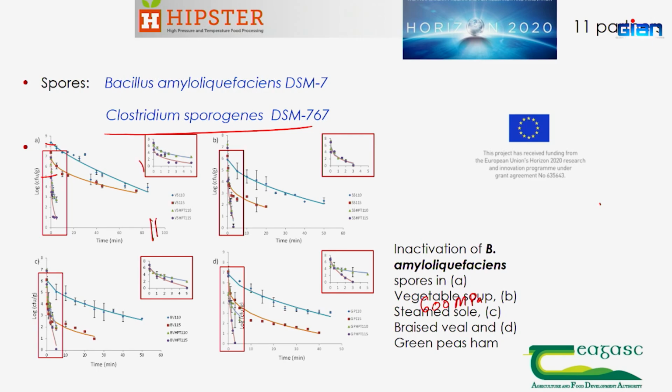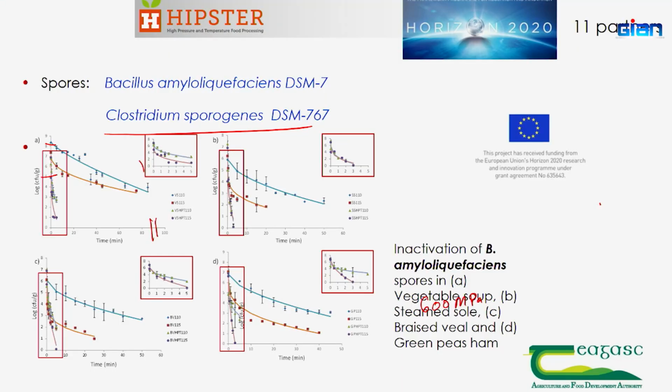Why was the limit set at 600 megapascals? Because if we go for 700 or 800, we can reduce the time even further, but the strength of the material becomes challenging. The design aspect here was that whatever vessel is to be used is preheated to a temperature, then it goes for high pressure. Otherwise, you have to heat up the whole vessel where we are generating the pressure. By doing so, the amount of energy required to heat up the whole vessel and the strength of that material, number of cycles are reduced. So, what you see here, temperature alone takes longer time.